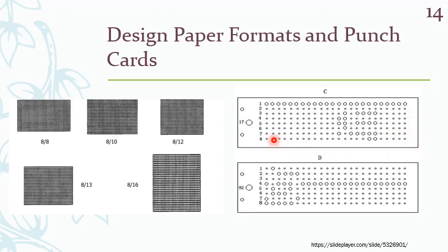The size of this card depends upon the number of hooks available in the jacquard. Generally the number of holes in a short row can be 8, 10, 12 or 16, depending upon the format of the hooks available in the mechanical jacquard. The punch card will have the format accordingly, and its length or size would be such that it will accommodate the hooks. So the number of holes in a short row can follow a specific pattern 8, 12, 16, but the number of short rows in a long row will depend upon the size of the jacquard.